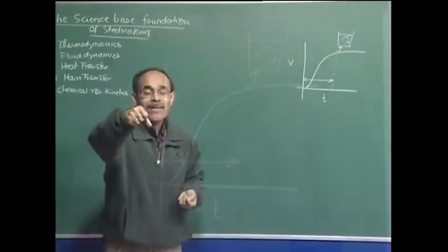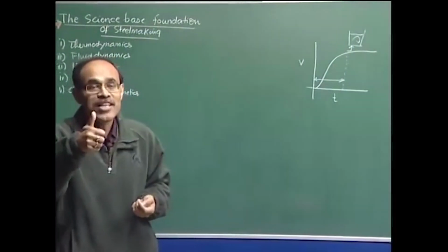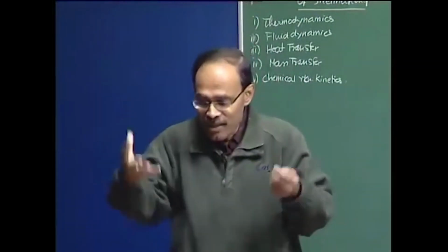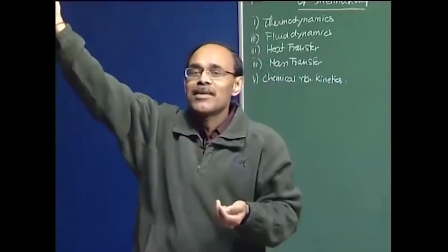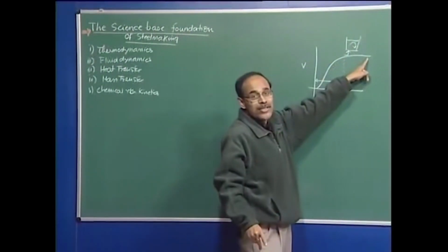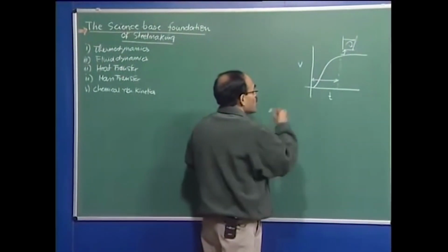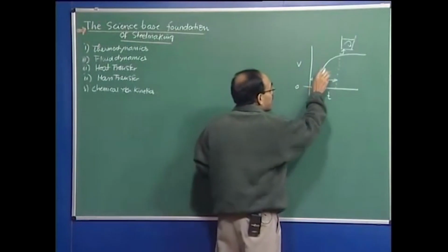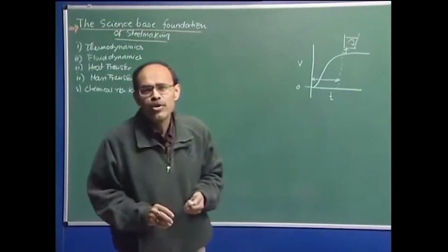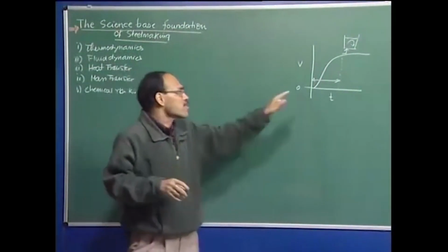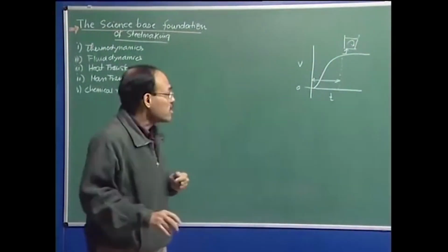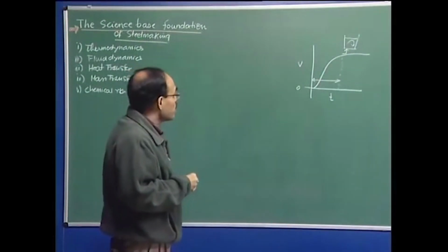Just like the way you take a kettle of water and you try to heat it. Initially the temperature of water is going to increase, and at some point of time the rate of heat input to the kettle will be exactly balanced by the rate of heat loss, and then you are going to hit a constant temperature. That is the characteristic also exhibited in this particular case. From 0, the velocity is 0. So, the velocity starts to increase as we introduce gas, and then eventually the velocity becomes a steady state. So, it depends on the process which we are looking at. If you are looking at the initial period of gas injection, the flow is unsteady. If you are looking at a long duration of gas injection, in that case we can say that the flow is steady.